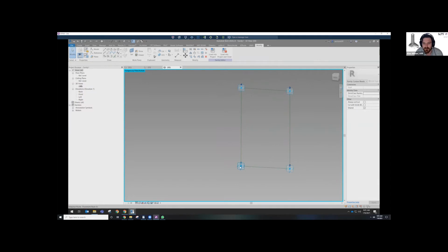Okay, so some important things to note. If you haven't used adaptive panels before, obviously they're based off adaptive points. If you do place a point here, it can be converted to an adaptive point by changing the point over here to adaptive. You can see it will get a number based off the other points located. So if you have 4 points and you add another one, that will be the 5th point. It just counts like everything else in Revit does.